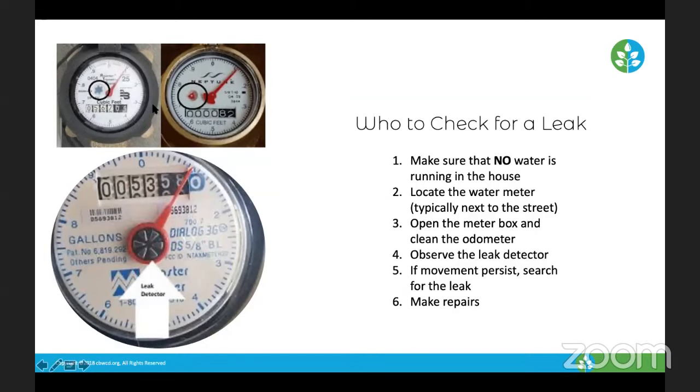So what's a low flow leak? Let's say, for instance, when it comes to irrigation, our irrigation valve is leaking just a little bit. The water meter dial is not going to turn with very low flows. What you're going to find is this little indicator moving very slowly. In all of these cases, if you have a mainline leak, so in the main piping before it goes to the irrigation valves connected to the water meter, the leak detector will be moving.